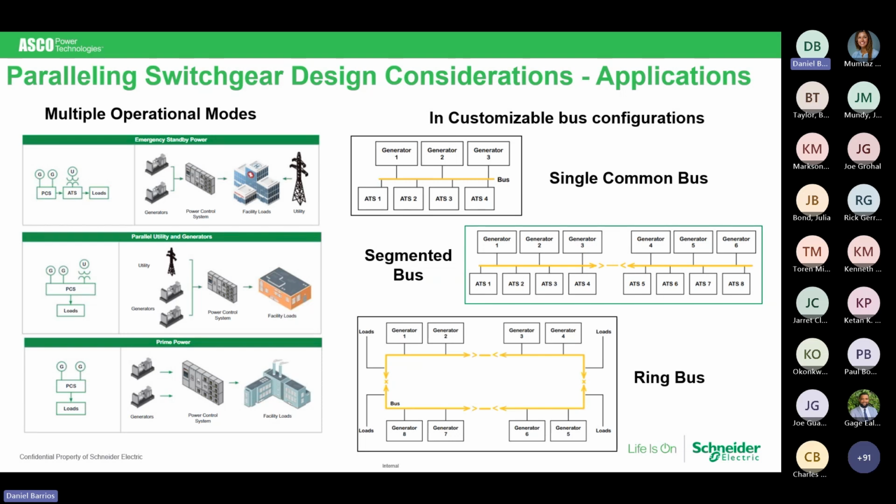If you're putting it in an e-house, a simple suggestion is that in lieu of a complete skin on the outside, you would put a set of doors where you can open the doors, make your terminations, and then close the e-house up. I've seen one application where it was in a cinder block type building, and the electrical contractor got quite ingenious by taking a part of the wall out, putting a garage door there where he could open the garage door, make all of his terminations in the rear, and then simply button it back up and close the door.